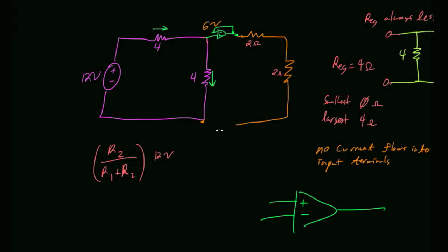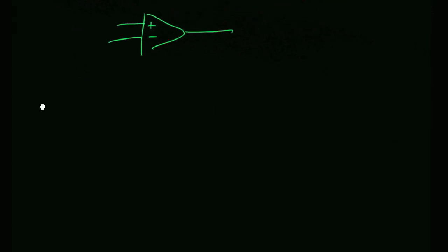Almost. Not the two inputs. Okay, so op amps work like this. You've got two inputs, a V positive and a V negative, and you've got an output. Now, the rule is always that the output of the op amp is equal to some big old gain, some big old multiplier, times the difference between V plus and V minus, between the two nodes. So you take whatever the voltage is on this node, minus whatever the voltage is on this node, times it by some great big number that's a property of the op amp, and that'll give you your output.